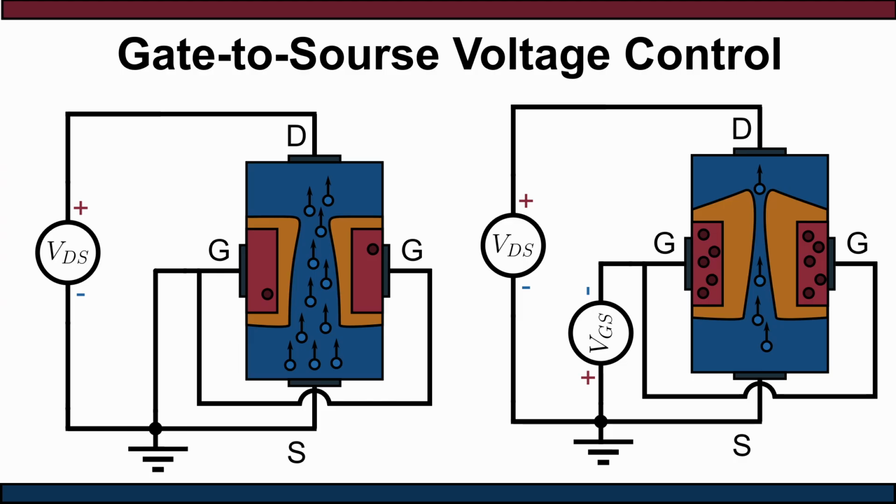If we put a voltage supply between the gate and source, it changes VGS from 0 to a negative voltage supply value. The electrons from the channel start to avoid the p-junction area and the depletion region spreads wider. This reduces the channel and the current through it. As a result, we can regulate current flow by VGS. To make it more clear, look at the other illustration. The channel is shown as a tunnel where electrons are moving upward from source to drain. The gate regions act like walls that can expand into the channel.